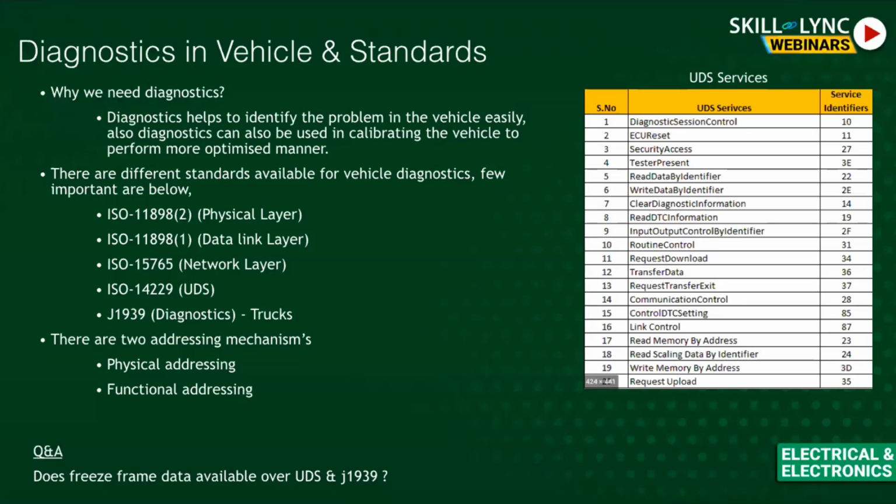One is trying to transmit to 2, 3, 4, 5, but one wants to transmit only to 5, but not to 2, 3, 4, right? In that case, it can use physical addressing. It can utilize only the fifth address, but not the 2, 3, 4 addresses. Only the fifth address alone it can use, and it can transmit the message. So the one-to-one communication I was talking about is physical addressing.